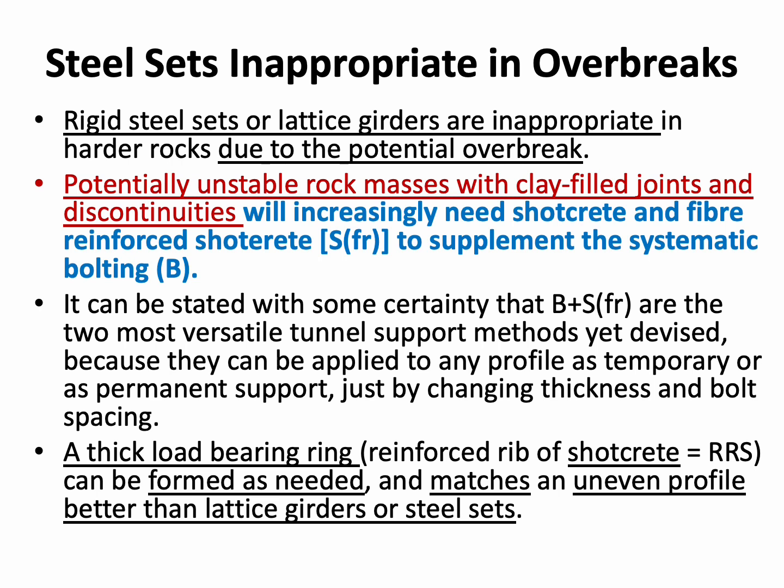In the Norwegian method, the potentially unstable rock masses with clay-filled joints and discontinuities will increasingly need shotcrete and fiber-reinforced shotcrete to supplement the systematic bolting.